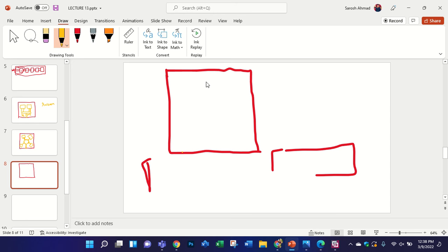Like this one, there is also another technique. If you want to make multiple antennas, you need to use a feed line, the length near to the length of the substrate. And then you can create strip lines here, and also here. And this line is of 50 ohm, this feed line.